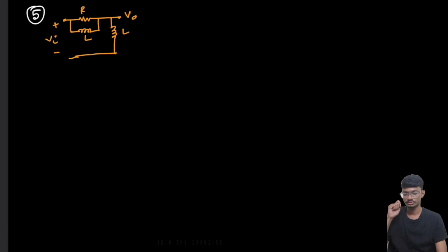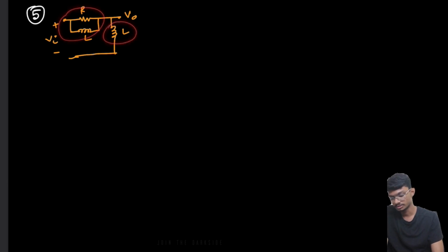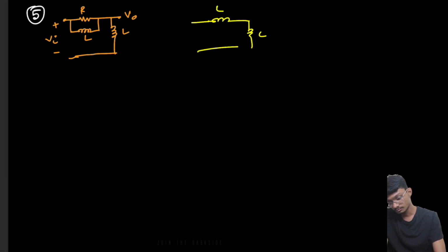So here we have the next question. This is basically a similar type of question only. Can we short the output this time? We can't, actually. If we again short this, this is Z2, this is Z1. If we again short this, then the equivalent circuit will look something like this, and the gain is not 0 at that stage because Z1 is going to 0, hence we can't short the output.